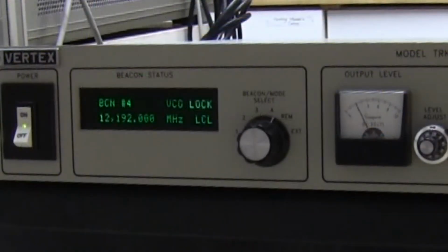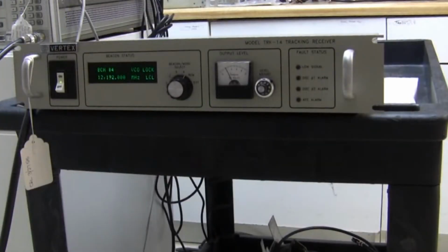It gets input directly from the LNA, so it's getting KU band frequency, as you can see at the moment. It's looking at 12192 megahertz. The first understanding is that the satellite does not stay in a constant position. They can drift up to 1,000 kilometers. And when they do drift, the Earth station antenna has to be adjusted very slightly to stay on track.